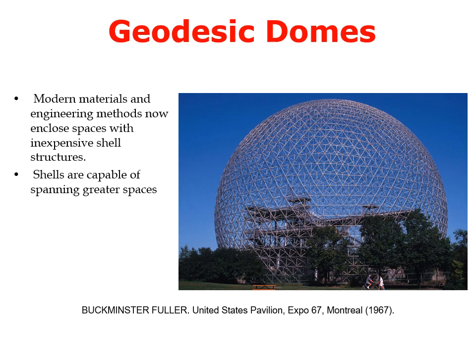Then geodesic domes. Buckminster Fuller came up with the idea of the geodesic dome, and it's all based on the use of the triangle. You look at the structure, and it's all a bunch of triangles put together in different ways and different positions, and again, it becomes this massive self-supporting system, so that you have this nice, large, unobstructed area on the inside.